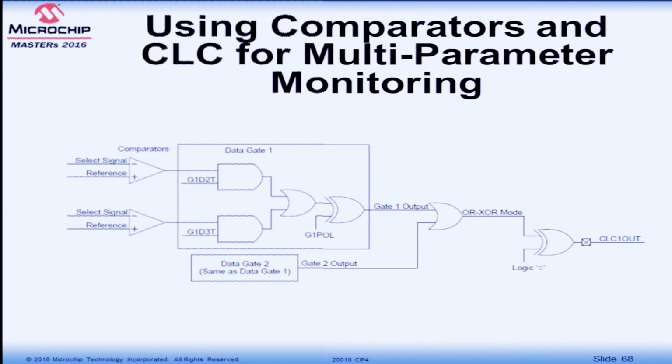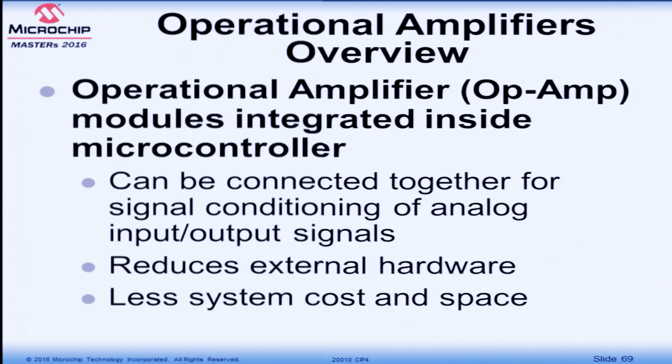And then there could be multiple such parameters that you are combining in an OR gate. So finally you will get one control signal that you can directly use to shut down some piece of machinery. There are various things that are possible just using the basic functionality of the CLC, AND gate, OR gate and so on, not even any sequential logic.